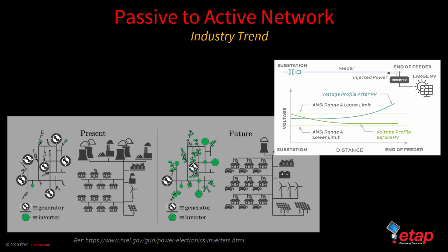And the effect of a large PV system or large groups of distributed PV systems is such that as the real power is being injected into the feeder, it tends to unload the feeder by providing that required real power at the local level, causing the voltage on the receiving end of the feeder to not drop but essentially climb. So the intermittency of the PV at the end of the feeder has a reverse effect on the voltage profile at the end of the feeder, and therefore must be accounted for on a continuous basis, which again cannot be done through just standalone controls or simple rule-based approaches.